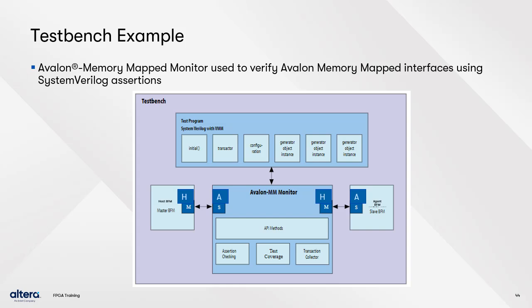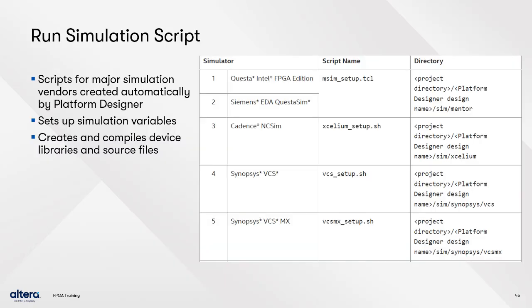The Avalon memory mapped monitor also includes a transaction collector feature to collect and monitor transaction status. You can find this and other applications in the Avalon Verification IP Suite User Guide document. Once the test program is created, you can modify, then run the simulation test scripts.